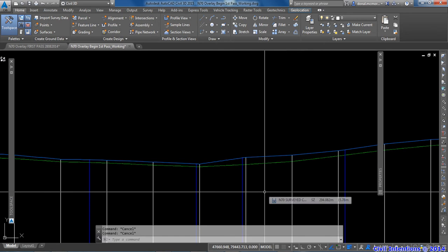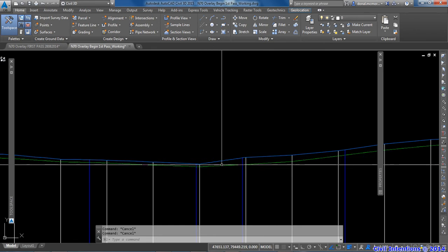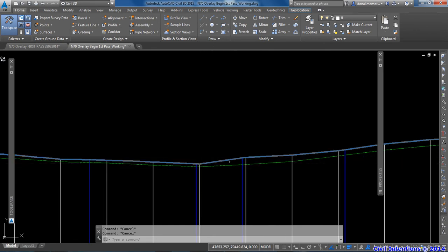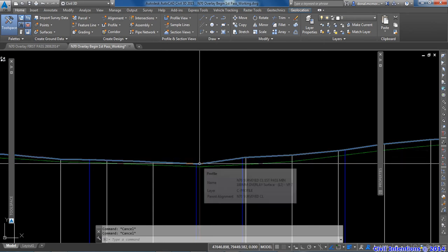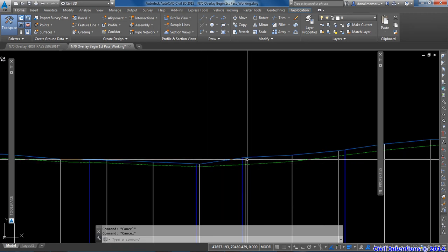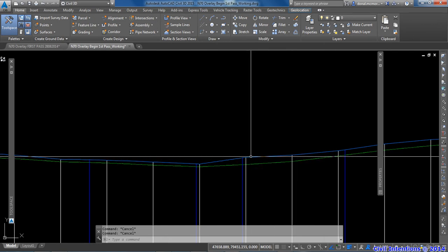Okay, and this is one of the main reasons that you need to do the first pass and treat it as a first pass only, because the Civil 3D overlay tool has produced this kind of result. So basically at this cross section it's analysing the high point, applying its criteria, its minimum depth, the high point, and so on. And then at the next section here, there's a big jump up because there's probably a localized high point at this location or at this series of locations.